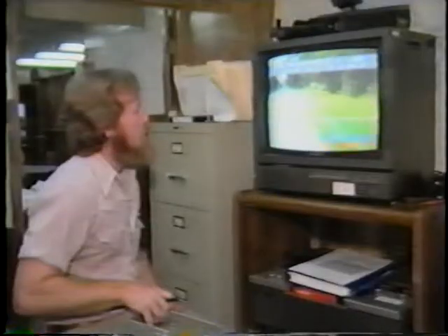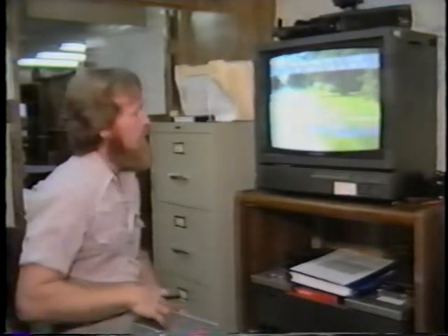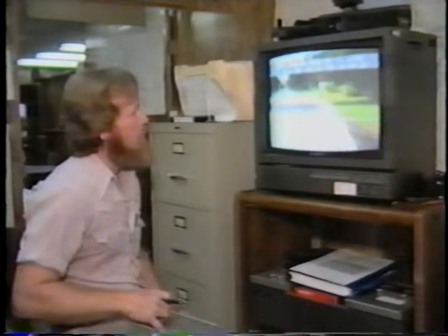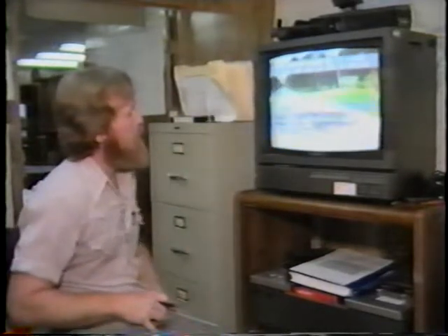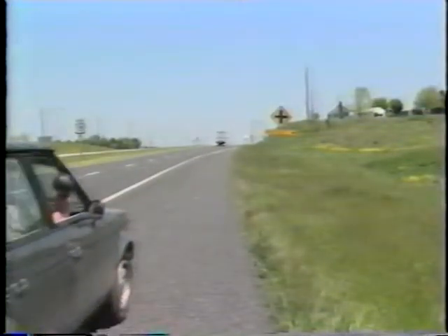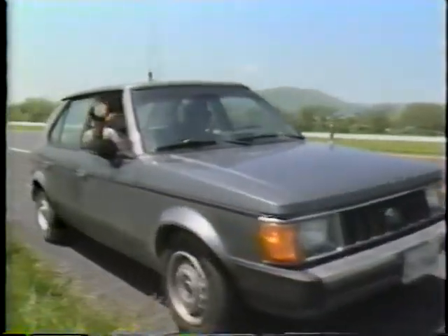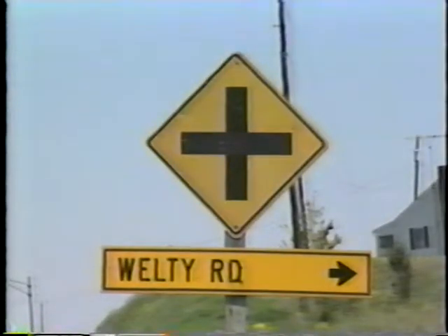The first task normally associated with an effective sign maintenance program is to conduct an inventory of all signs presently in the system. There's a wide variety of ways to conduct an inventory, from video logging to manual recording out in the field. Whatever the method, a sign inventory is the best first step an agency can take to begin taking control of its signage problems.